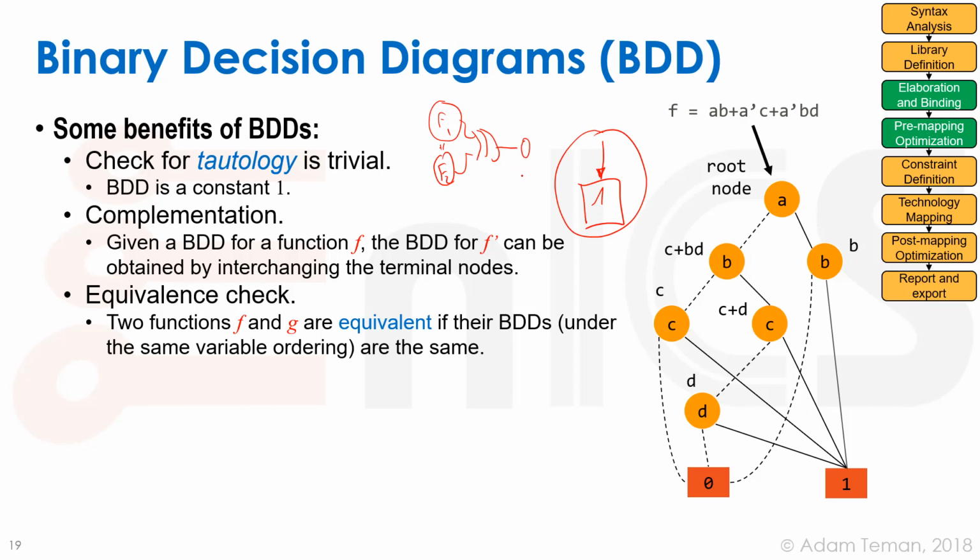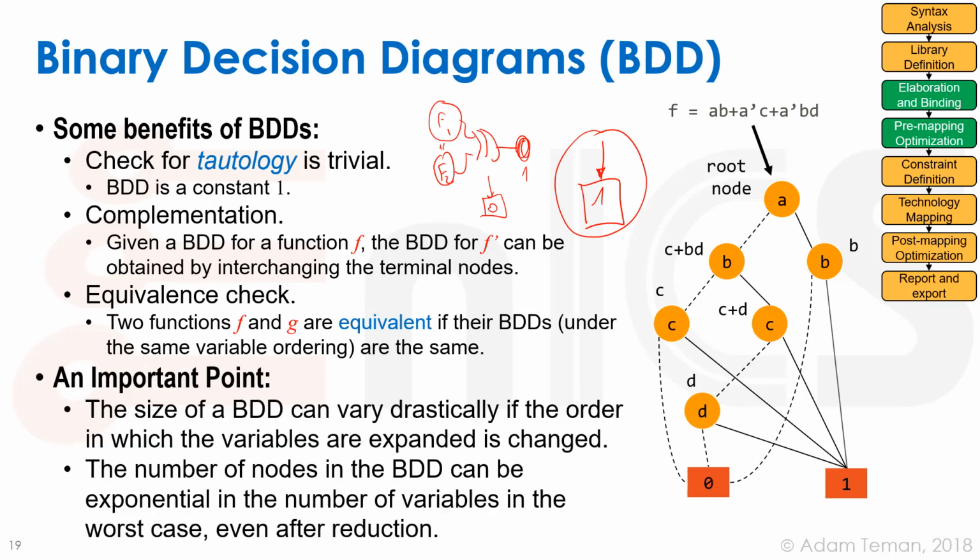And if they are not equivalent, we will get a 1. If it's a 0, that means that after we apply our reduced order BDD, we're just going to have something like that. So it's really easy to do this logic equivalence check, and this is one of the things that are used in logic equivalence checkers from commercial tools for formal verification.